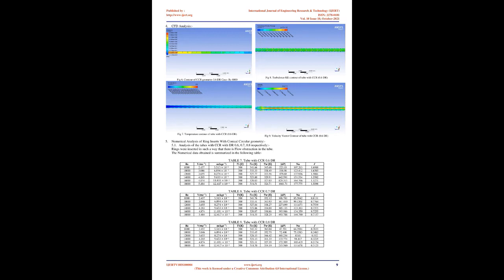The numerical studies were carried out with a uniform velocity profile at the inlet of the pipeline. The direction of the flow was defined normal to the boundary. Inlet velocity and temperature were specified. Turbulent intensity, I, and the hydraulic diameter, dH, were specified as 5% and 0.0485 m, and an outflow boundary condition was used at the pressure outlet boundary.